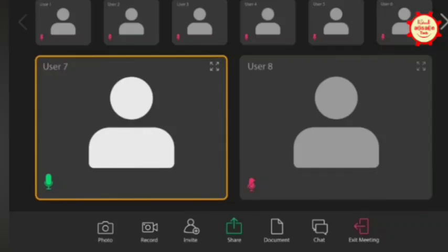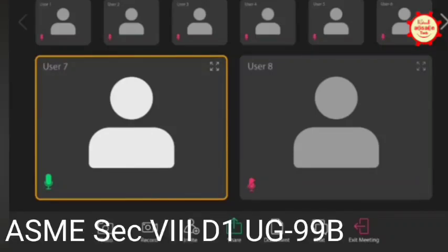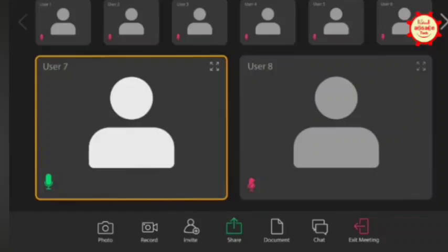But in the last day in the group, I think the conversation was that they will not allow it, for the gasketed joint as well. I think that's not correct actually. In earlier addenda, they used to mention that in UG-99(b) only, but now I think they shifted it somewhere else in the code that we need to search.